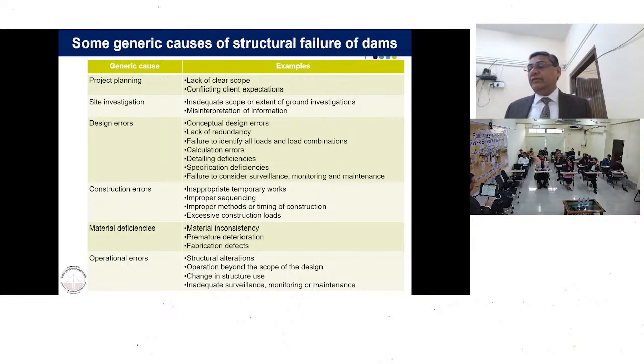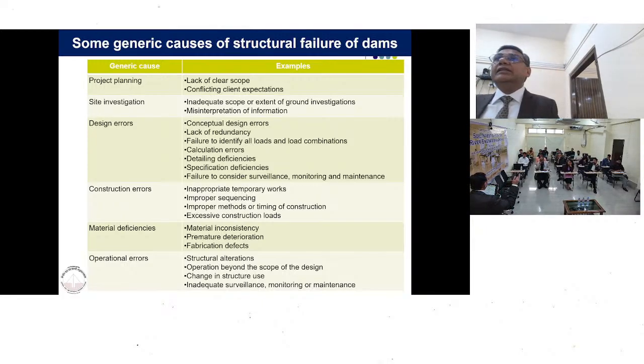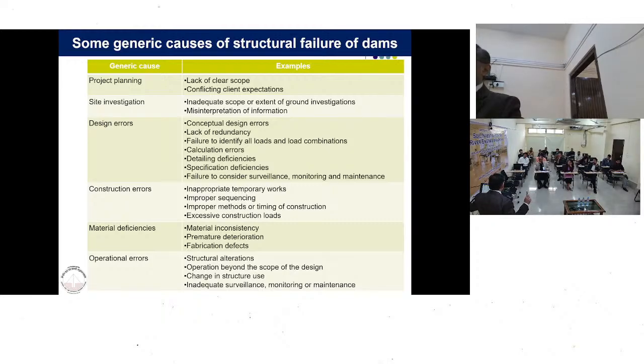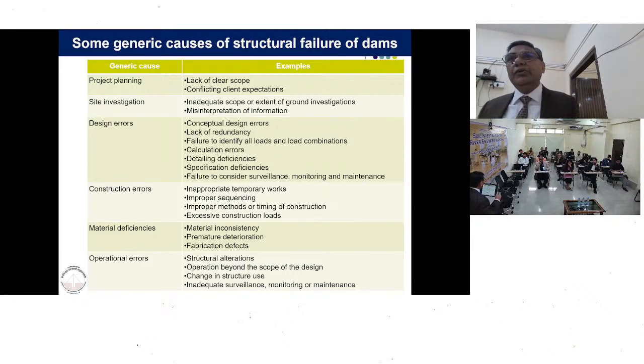When we reached there, we saw how these things were affecting the whole structure. We asked the project people to at least clear the bushes, as we wanted to see the abutment. When they cleared the bushes, we found that the hill slope was coming like this. So our basic planning of putting the earthen dam abutting this abutment was failing. The rock cores were showing that you cannot go for a concrete dam, and the survey which showed that you can go for an earth dam was now failing. Then we had an interaction with the survey people. How did you do the survey?